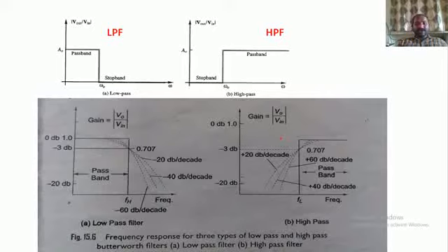Okay, now if you see this, we have 20 decibel now. Minus 20 is nothing but reduction now. Means how far? A decade means 10 times the input signal frequency. I can simply say that it is 10f. So the reduction means this is the cutoff frequency now. After this cutoff frequency, we are not expecting any frequency components. So this solid line is indicating the ideal characteristics of the low pass filter. After this solid line, we are not expecting any frequency component. But unfortunately, in the practical case, we are getting so many frequency components.